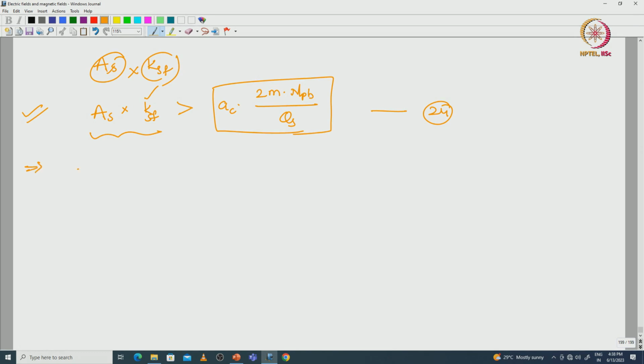Next we have to find the number of laminations. This we can do at the end, or at the starting of the stator core design also. Anywhere we can find how many laminations are required. The lamination thickness will be 0.1 to 0.5 mm depending upon the material and flux density values.